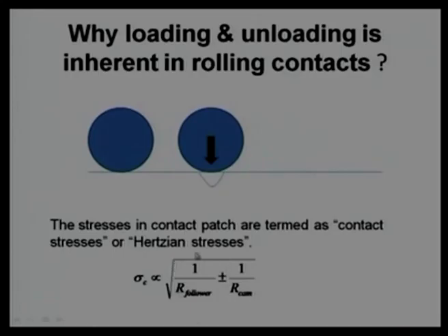We can say that a convex and concave interface will induce lesser contact stresses compared to a convex and convex shape. That is why we need to always think over whether we really recommend a convex-convex or convex-concave interface. And as I mentioned, in our case study or cam follower study, both the combinations are there.